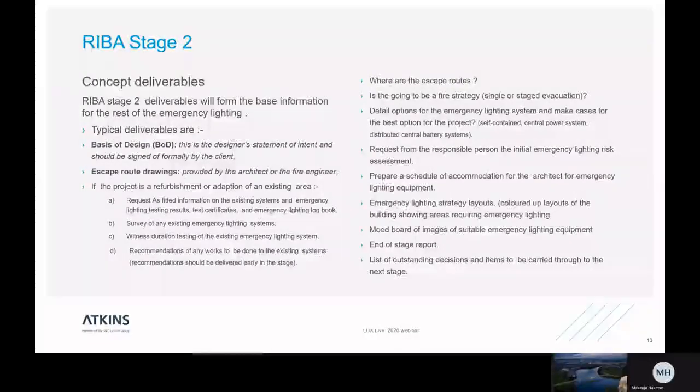Do you stick a big luminaire on the wall with a green LED showing that it's there, and when you look across a darkened space, you can see the green LED with a great big patch of green light on the ceiling? So you have to think about how that's going to look. There is a requirement to think about the effects of the emergency lighting early on, and this should all be picked up in the end of stage report.